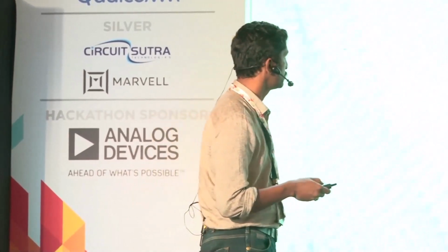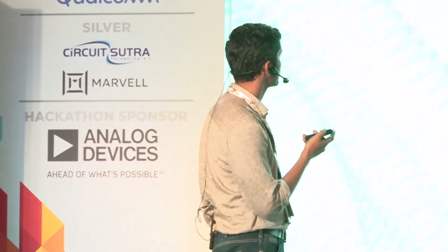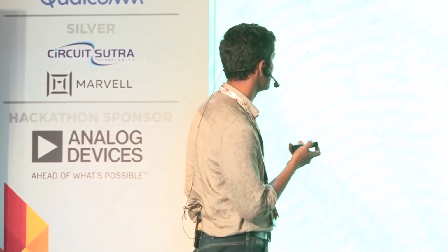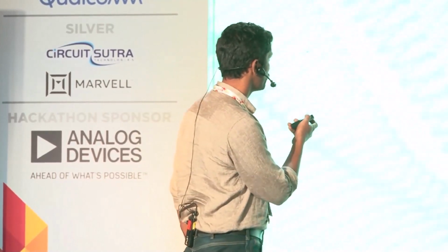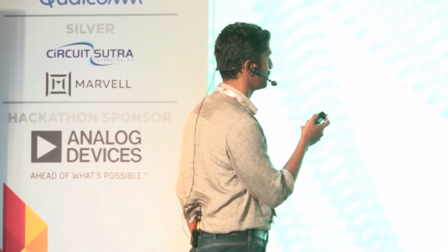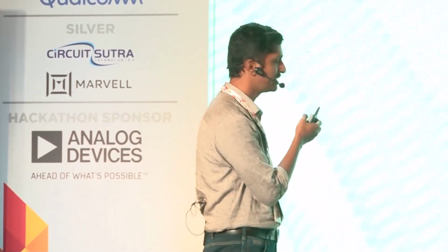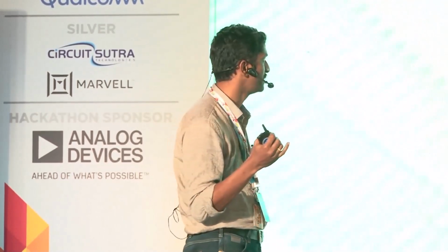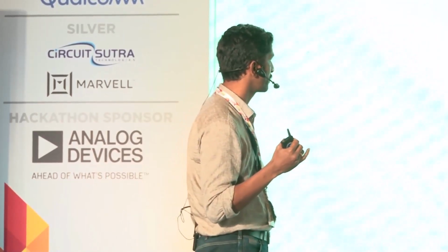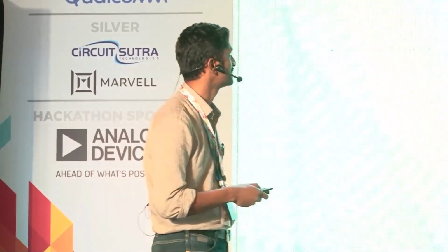Along with doing these structural checks and DFT checks, we also do these auto-formal checks, which detect dead code, FSM reachability, and FSM deadlock and livelock. It can also detect arithmetic overflows. We will discuss these in detail.